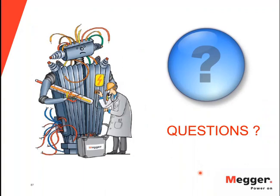Good morning, everyone. One of the typical questions will be if I have to test all the taps or not. The first question that we need to ask really is, what kind of testing are you performing? Is this the commissioning testing? Is it factory acceptance testing? If that is the case and you're commissioning and you're doing the acceptance testing in the factory, then I would prefer to test every single tap available in my transformer.